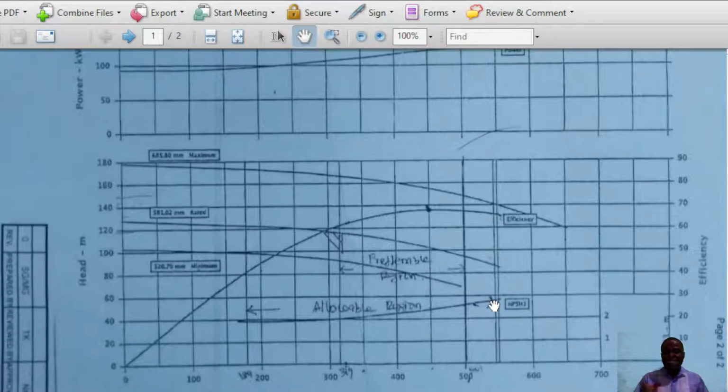So when you put this into the expression, your suction specific speed will be around 14,092 for this particular pump. You can check. However, you see, the most commonly used hard limitation for pump suction specific speed is 11,000 US units.